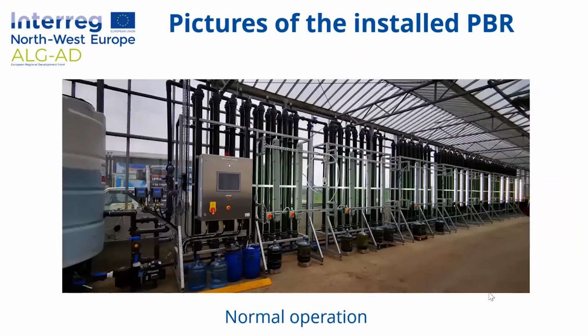And then this is the last slide I'm going to show really. So this is the reactor operating in normal operation mode. At this point in time, you'll probably notice that the tubes themselves in the serpentine reactor look black. These tubes actually have dense algal culture in them. So you can see it grows and becomes a very, very dense culture. We get up to something in the region of about 2 to 4 grams per liter in this reaction system.